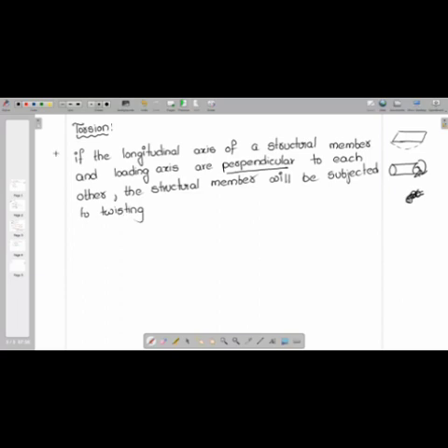Okay, so here, my dear students, if I take a beam like this, a canopy beam, and if you apply a load here, this is a beam, this is a slab, and this is a beam. Here it will be subjected to what, sir? Twisting. This is a canopy beam, or you can say an isolated L beam. Or the best example is grid support.